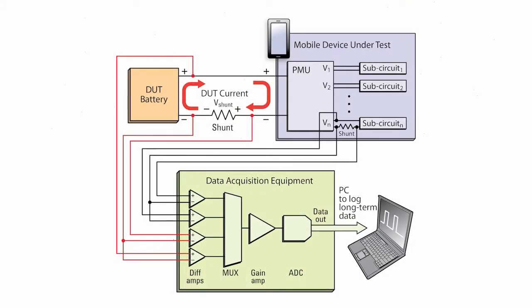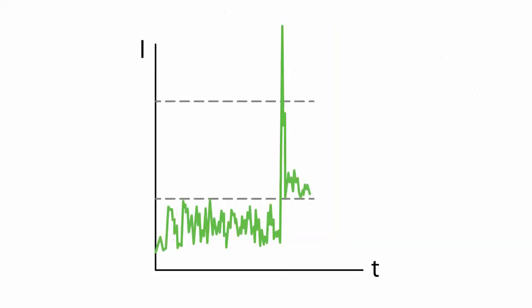Here is a setup using conventional data acquisition equipment for measuring a battery input at the same time as the subcircuit voltage and current. High-speed digitizing of the current is essential, as it provides many detailed insights about activities. Individual subcircuits often have much lower minimum currents, and therefore may need even greater dynamic measurement range than the overall device needs. The wide-ranging current drain usually exceeds the instrumentation's dynamic measurement range, limiting achievable accuracy.